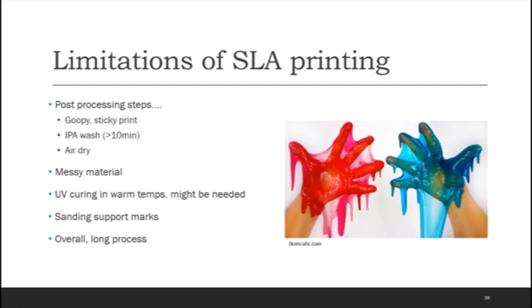Next, you have to use UV light to cure your print. This is mandatory for lots of the materials that FormLabs provides, but because we use clear standard resin, it is not mandatory to cure your print afterwards. However, it can help. We don't have a UV curing system at the CNS.